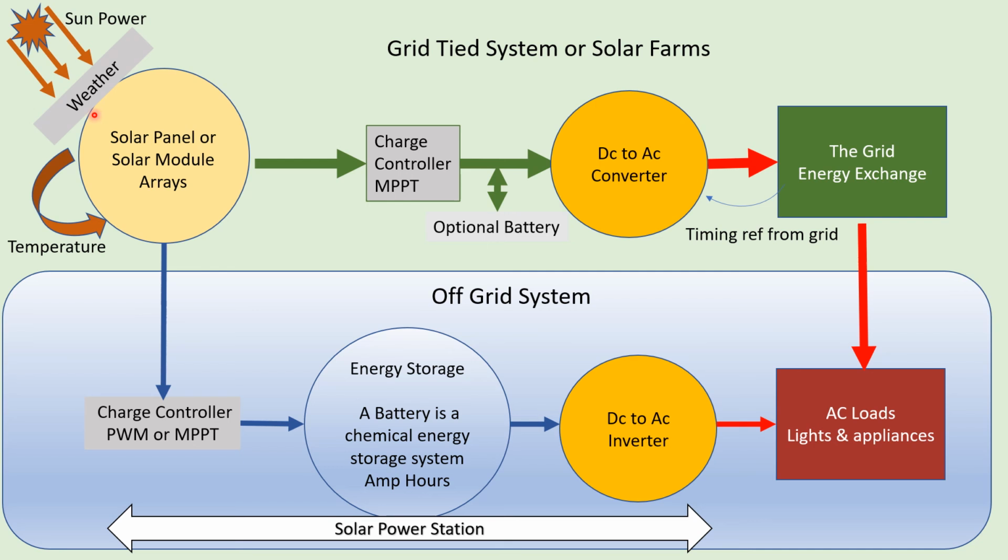And by the time it gets down to Earth, depending on where you live, it's somewhere around 1,000 watts per meter squared, unless you have water vapor in the air, dust, dirt, clouds, rain, snow. That weather layer is crippling. And if you have a storm, that's a lot of weather, that's a lot of loss of solar power.